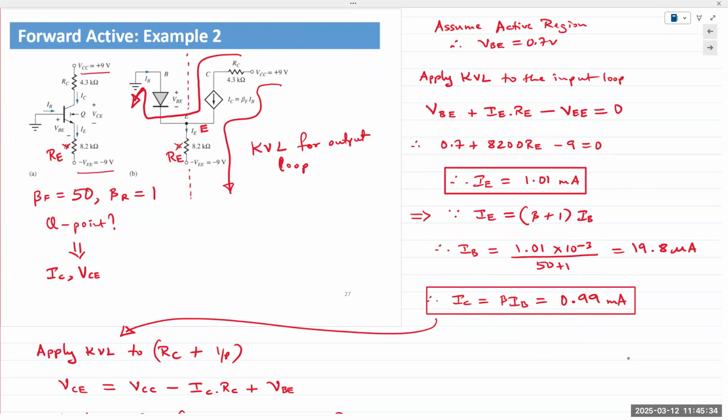Which one? No, it's a current source. It's a dependent current source. So right here in the center, you're asking about this? That's a dependent current source that indicates that the transistor is supplying a constant level of current at the collector terminal. But that dependency is on the input side. It's either dependent on VBE or IB. It's convenient to take IB, so we just write it as a dependent current source beta IB.